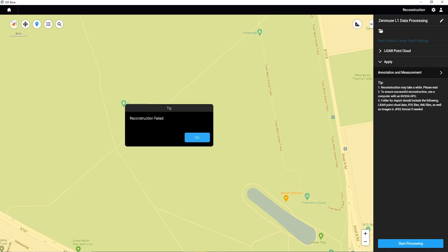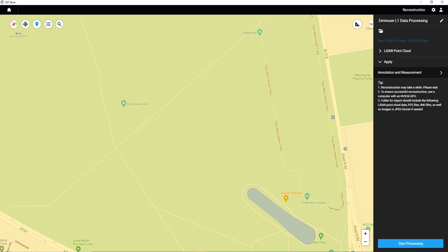If you receive an error message saying that the reconstruction has failed, this could be to do with the amount of storage available on your PC. Usually, if there are many active projects open in your DJI Terra directory, it will take up a lot of the allocated space, and future Lidar projects cannot be processed. Usually, if you can successfully manage to process low density point clouds, but not high density datasets, this will indicate you have a storage problem.